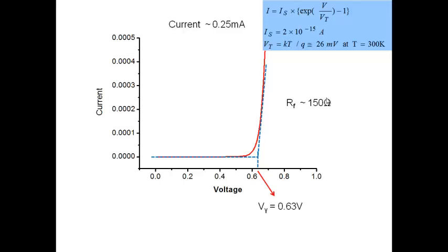So it's not really the resistance of the N region or the P region. Again, it's simply taking an exponential and approximating it. Depending on the current range, I may get different values of V gamma. I get a different value of RF here.